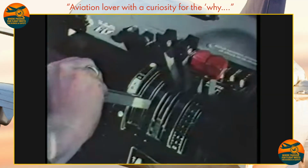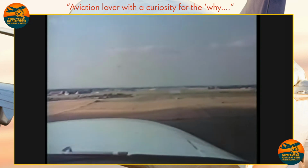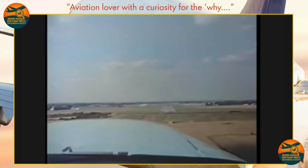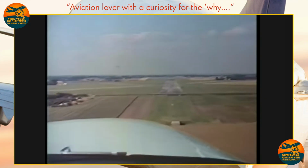This means that the pilot can use the throttles to accelerate air over part of the wing and thus increase lift, controlling the attitude of the aeroplane in pitch and changing or maintaining height with very little variation in speed.